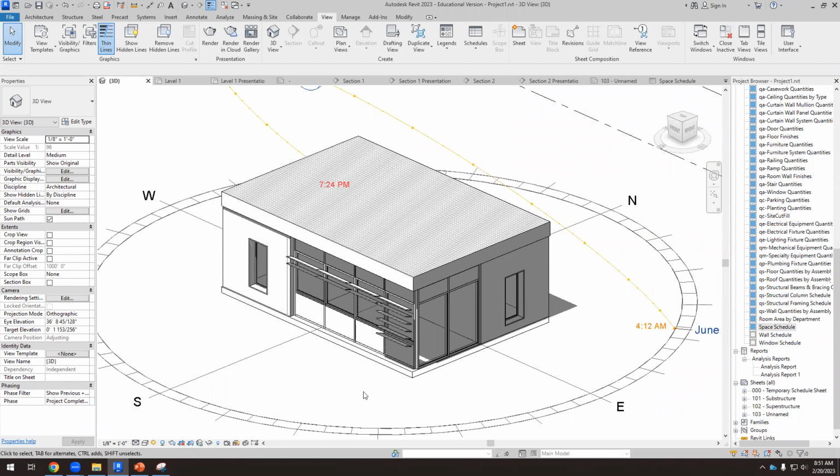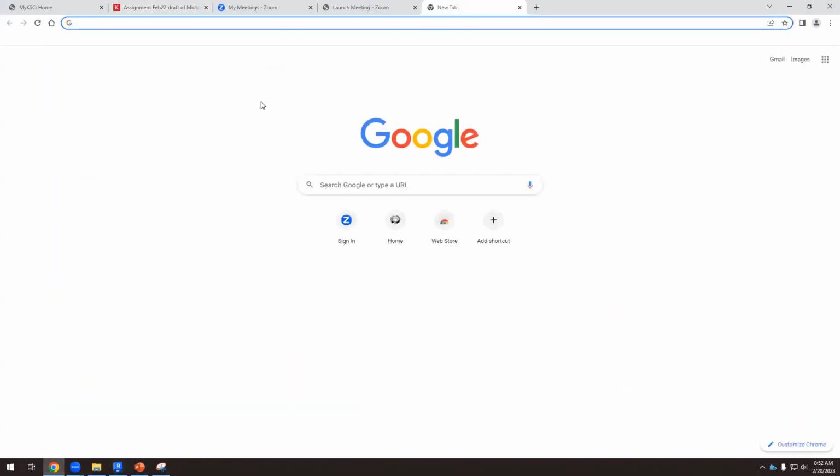Okay, so in Windows, we need to work with the catalog. For this wall, I can make up the wall. So I can say, okay, this is the gypsum board, then an air chamber, then thermal insulation, then brick, then whatever. And it's something that doesn't work with the catalog, because if we use the right materials and we specify the materials, we can do that. But with the window, of course, I can specify that I have triple glazing and low emissivity and the solar heat gain coefficient, but I need to find a catalog. Okay, so I'm going to post a catalog on Canvas, but if you find